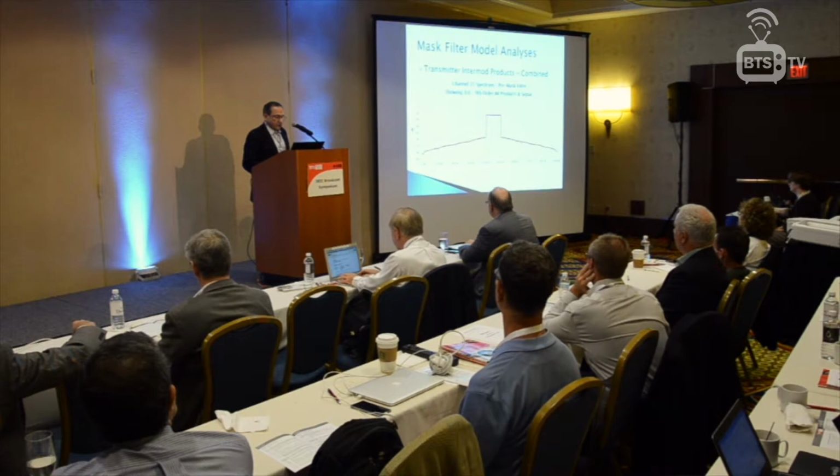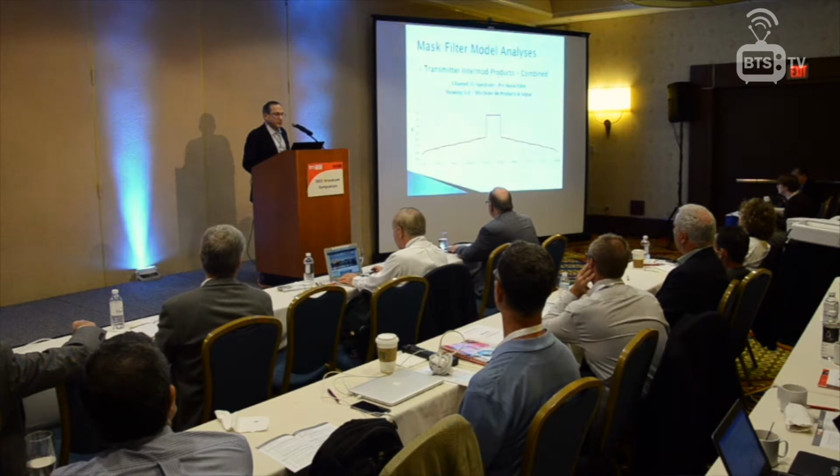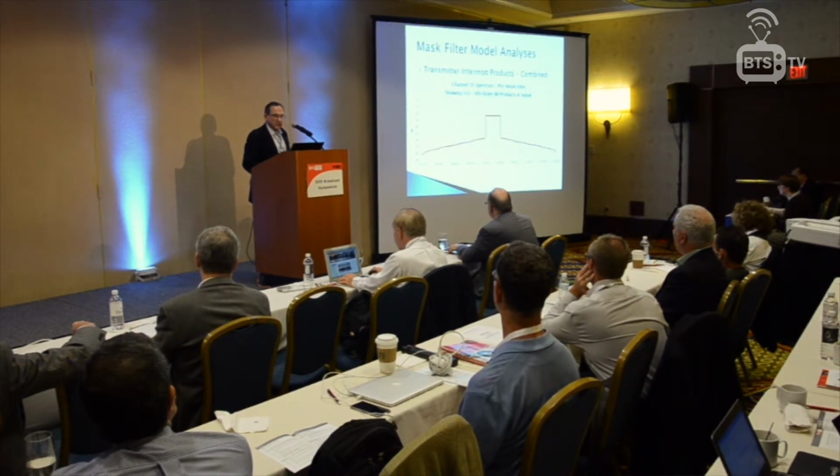And then if we start with 47 dB down in the first 500 kilohertz, which is what the FCC rules say about where the shoulders have to be, since we're talking about 500 kilohertz, that's 10 of those samples. 10 times the power is 10 dB.